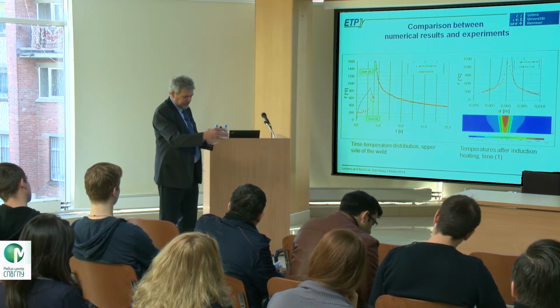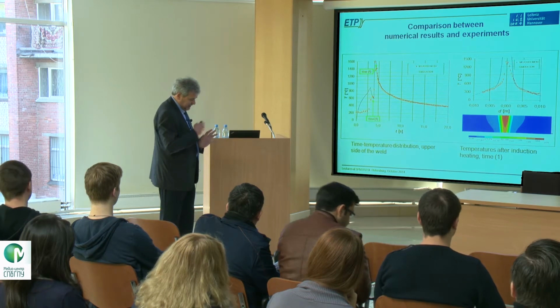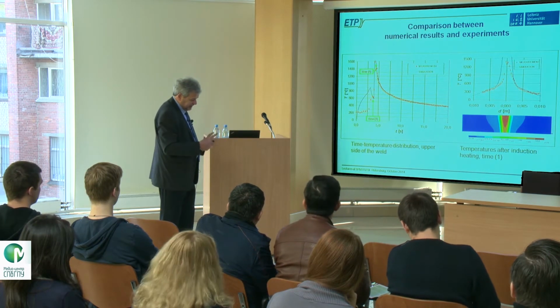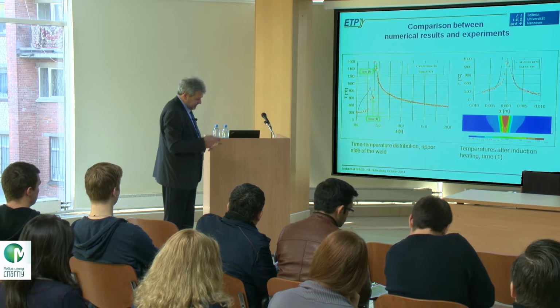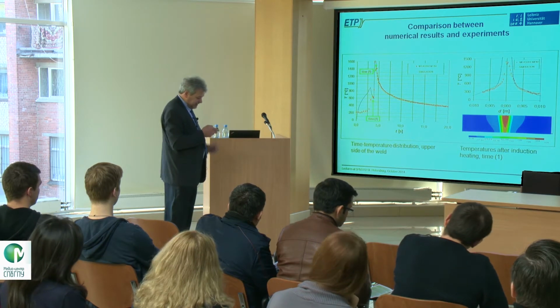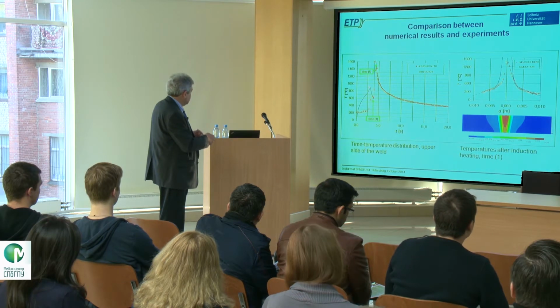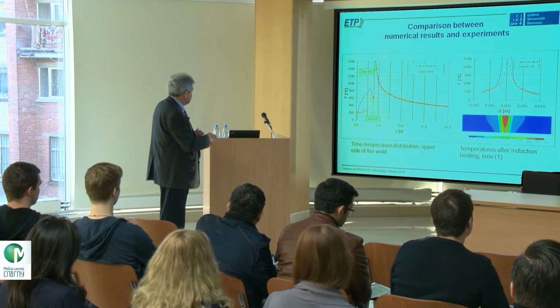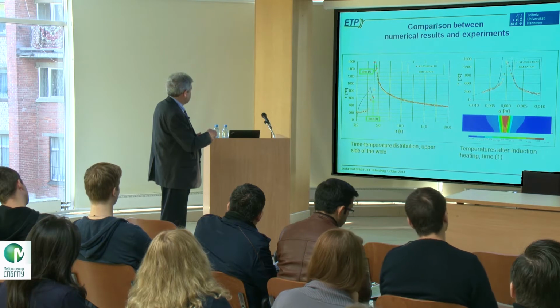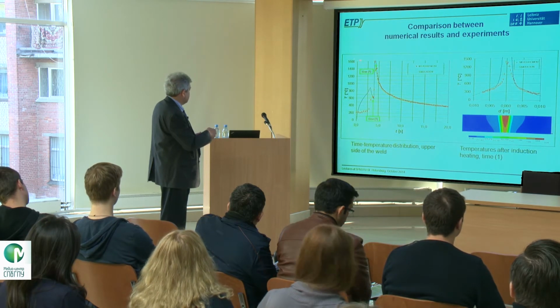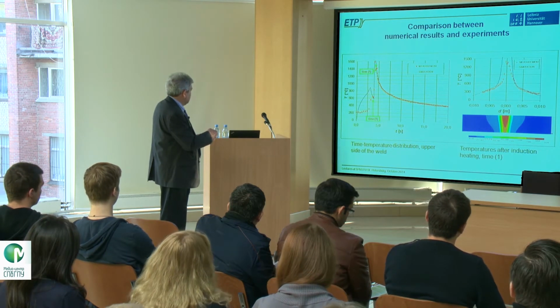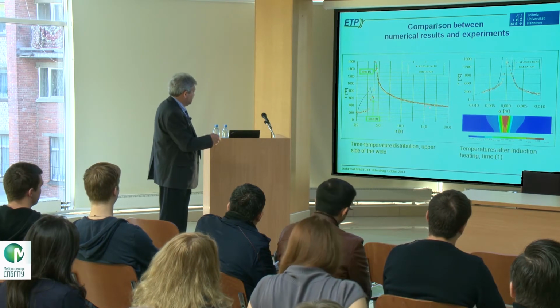You need a certain gap because otherwise you are influencing the laser by electromagnetic fields, by Lorentz forces, and also the laser can damage your inductor, so you need a little bit of space. And in this space, of course, you have a cooling down, and then the laser comes and brings it up to welding, more than 600 degrees centigrade, and then you have the cooling side here.